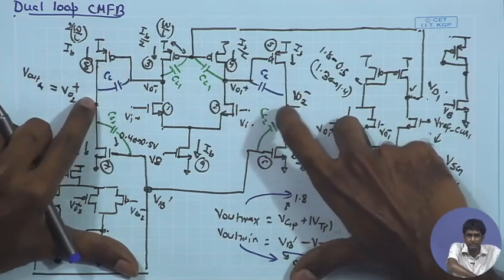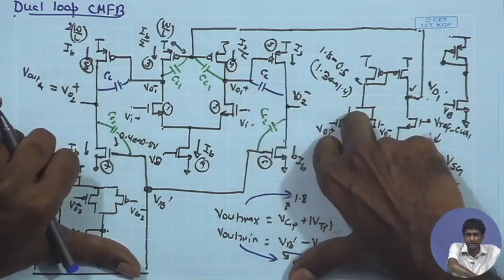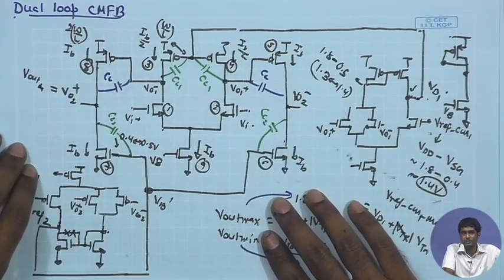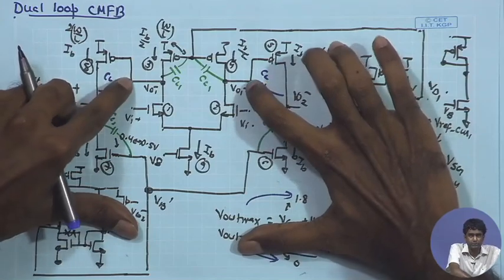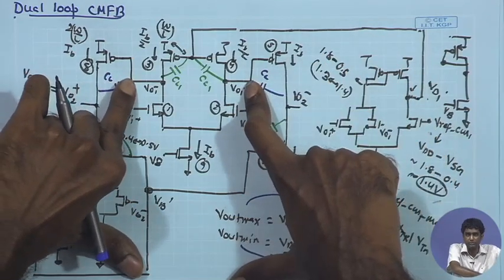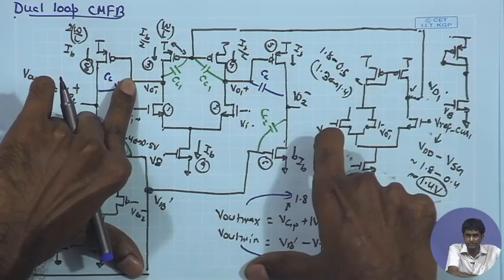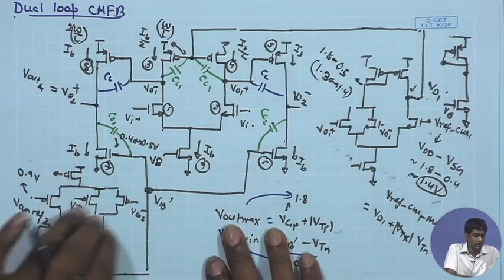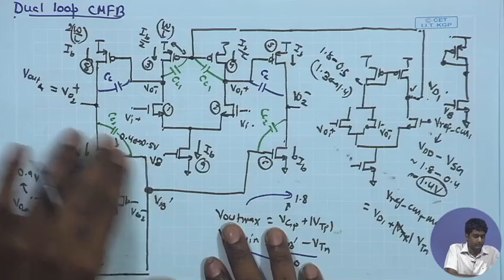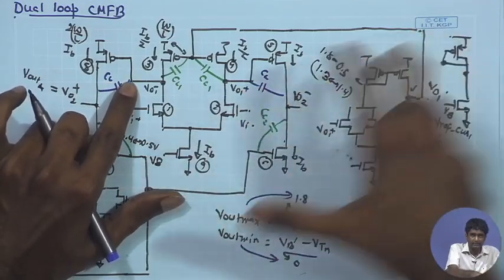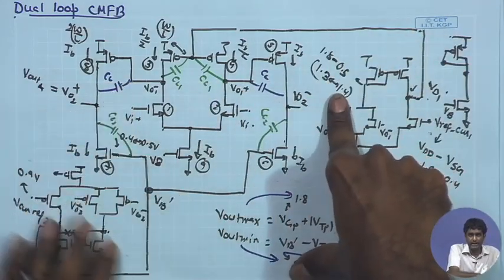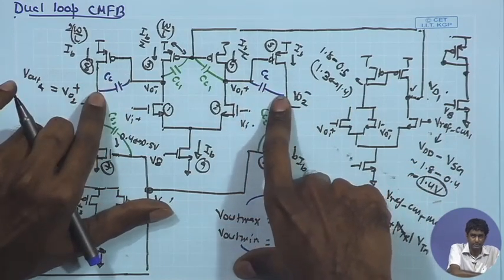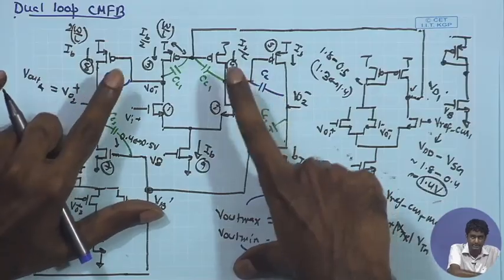Of course, it is in the reverse path, from this point to this point you do not have gain. So, as such you should not get confused about the multiplication of CC2 anyway, but even then we can see that this point is going to be relatively constant because it is being controlled by the common mode feedback of the first stage. So, while you are opening this loop and looking at the stability of the second loop, keeping the common mode feedback of the first loop intact, once again the CC over here just appears as it is between the output of the second stage and AC ground.